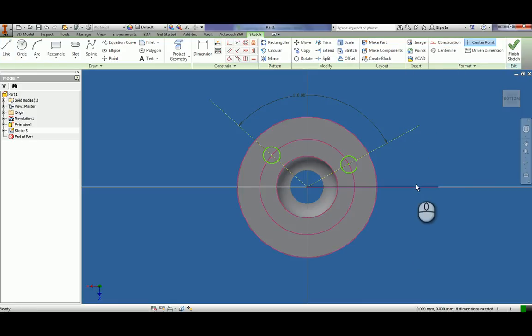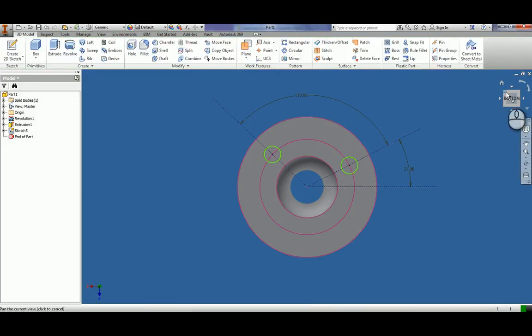That's going to be construction 2, so let's make that construction. Put one right here and here, and that's going to be 27 degrees. You notice how everything shifted over as soon as I typed that in, because everything is constrained together to move as one. So once you're done with this, click Finish.